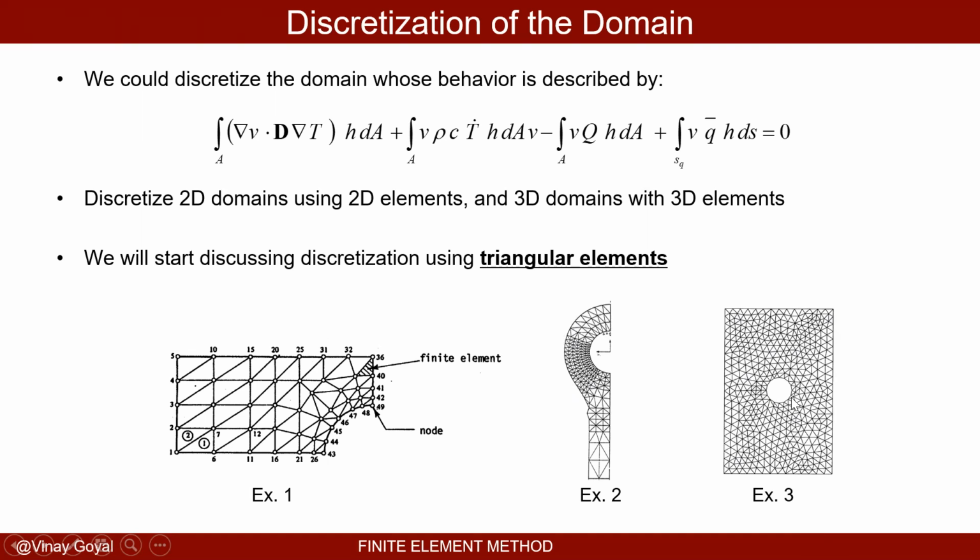And what is my goal by dividing the domain? It is to solve the partial differential equation over this subdomain and then be able to assemble all the elements together into a sensible solution. So triangular elements are quite popular. There's nothing wrong about them. They can do a fairly good job in general. But I'll discuss later the limitations you may find.